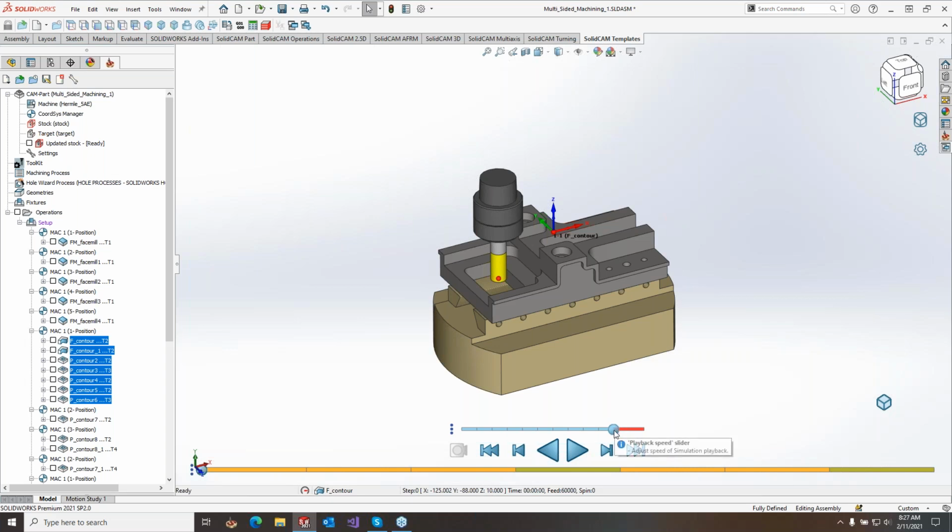And what this means is when we're on the first positions here, we activate multi-core calculation, and we also slow down the redraw rates. So normally when we're on the other positions, we try to do a smooth animation, which means we are simulating at about 30 frames per second, and we simulate every movement. When we activate these modes, we are going lower. I think we can go to a maximum of 1 frame per second. And we also buffer many toolpath points and do parallel or multi-core calculation.